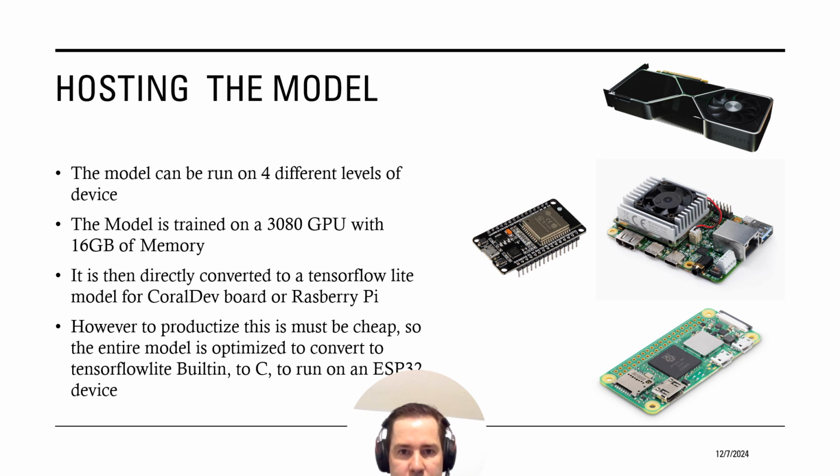Now, an IoT water meter isn't an LLM. The power and bill of materials budget means that we need to spend basically nothing on the processor. To this end, I designed the model 4 times, each in decreasing layers of complexity. The Edge Compute Coral Dev is capable of both training and running the model, but still has a power and money budget more than 10 times higher than my goal. The Raspberry Pi is again limited by the lack of a dedicated ADC, meaning additional hardware is required. The ESP32 was the ideal device, but it requires serious optimizations once our model is designed.